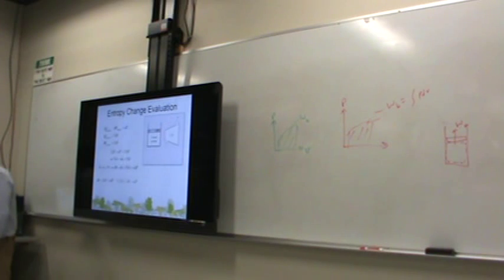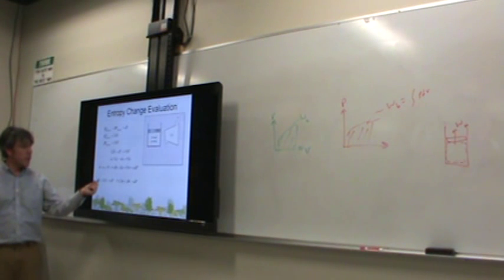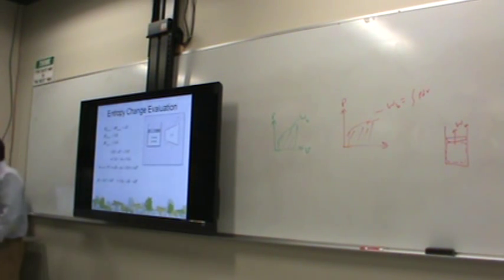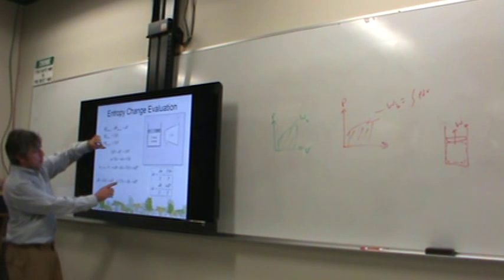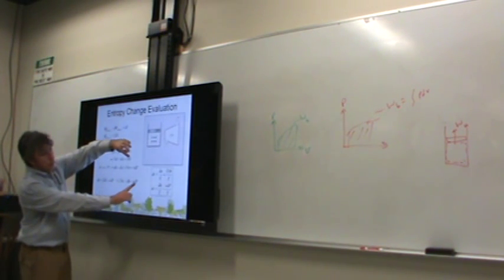Now don't worry about all this derivation. It's not all that spectacular or anything. Now let's solve for TdS. Just move the VdP to the other side. Flip it around. So we've got two different equations that allow us to talk about TdS in terms of enthalpy, internal energy, and volume and pressure.